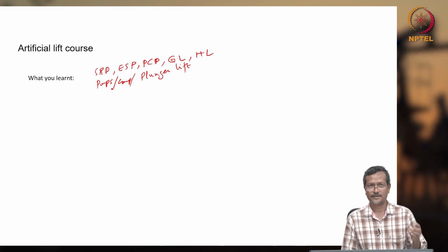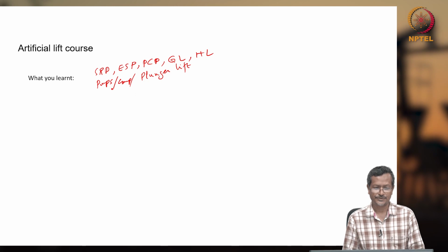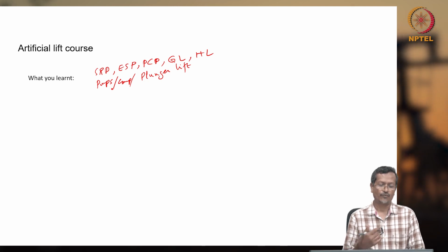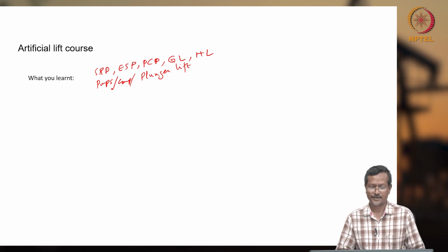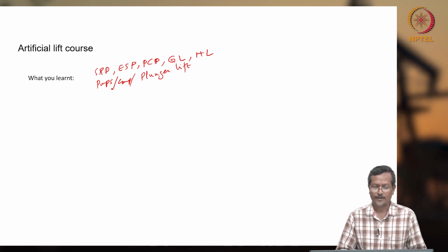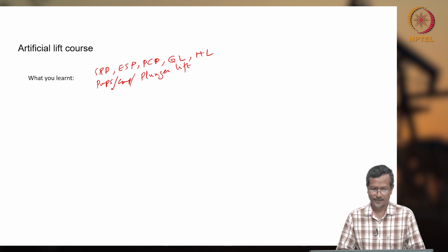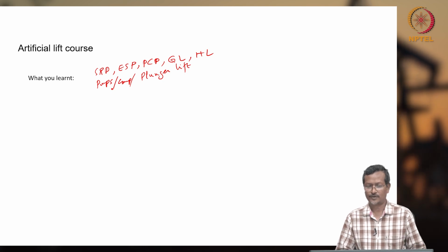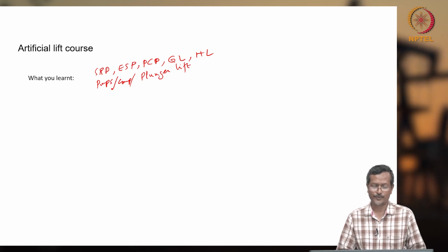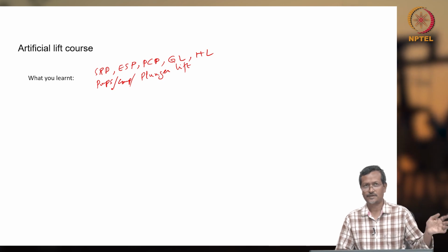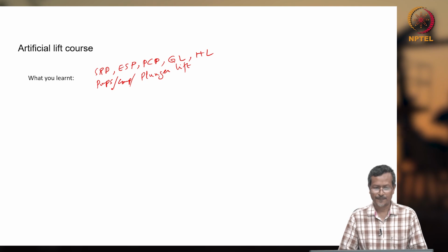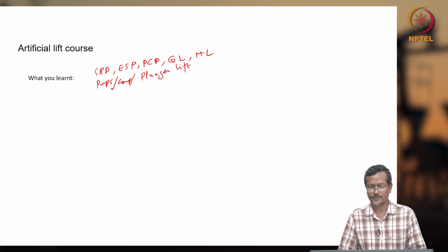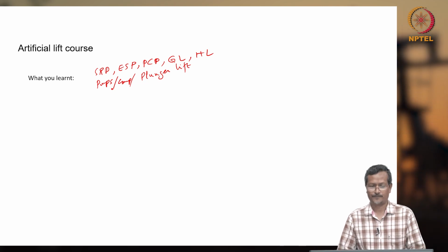If there is very high gas, there will be a problem of gas lock or fluid pounding, okay. But for low flow rate applications, like gas well liquid loading, where a small fluid flow rate is there, SRP is very good. For ESP, higher flow rate is fine, and horizontal, vertical or slant wellbore does not matter, but SRP has difficulty in horizontal systems. For a very long wellbore or offshore wellbore, SRP will fit, but ESP can go anywhere.